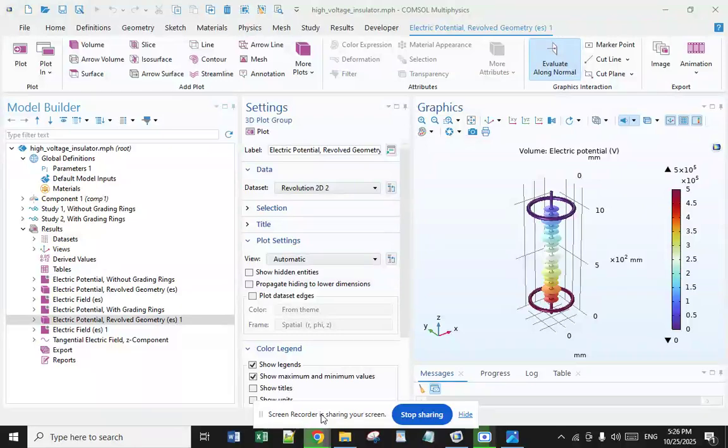And what about the selection considerations? When selecting suspension insulators, it is important to consider the voltage level of the line, the expected environmental conditions, and the maximum mechanical load. It is also crucial to choose suitable materials for disc and hardware, ensuring optimum resistance to corrosion, wear, and environmental influences.